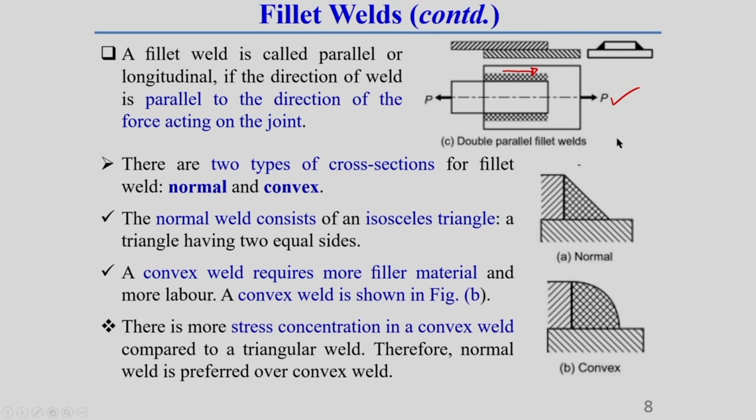Here you see this force is acting, and this is the force line of action, which is parallel to the fillet weld length. So, here the loading direction and the fillet weld length direction are parallel to each other. So, this type of fillet weld is known as a longitudinal fillet weld, or a parallel fillet weld.